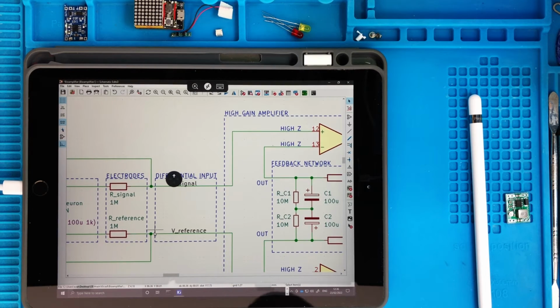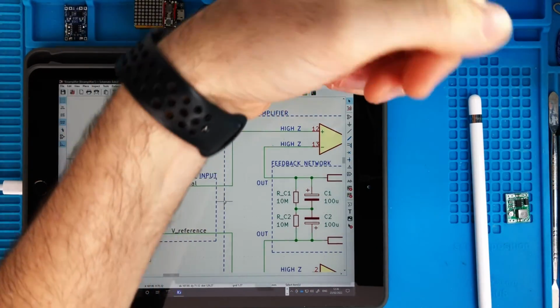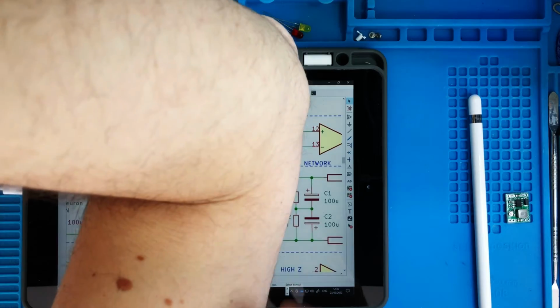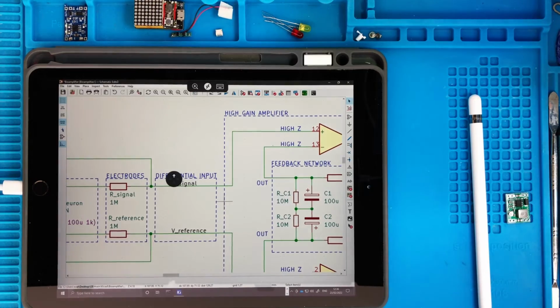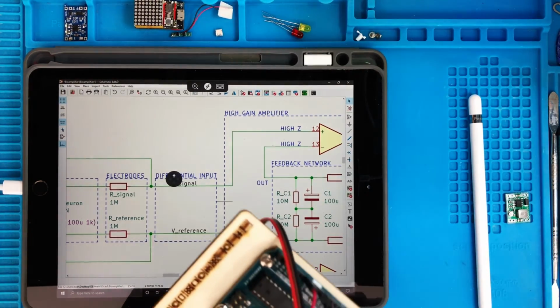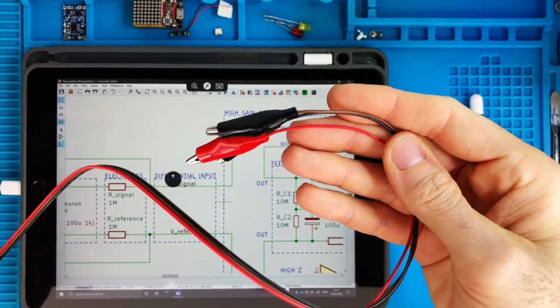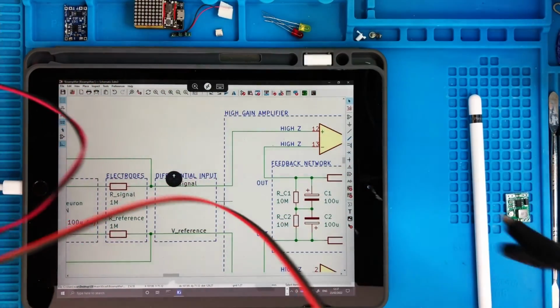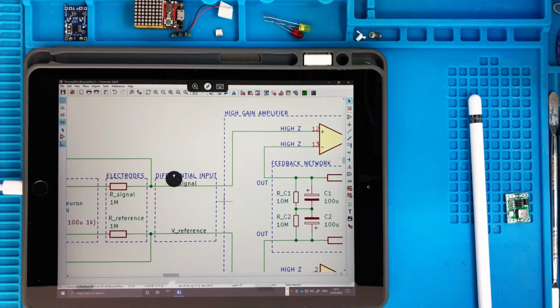Then there is a piece of wire which is a physical line. So there is some physical space between the neurons we have in the hand or in the arm attached with the electrodes, if I put my electrodes here, and the location of the circuit. So I'm speaking about those long wires here, the ones that go to the patch electrodes, and on the other side to the amplifier. So this thing is like an antenna. It can pick up noise, and this will be detrimental to our signal.